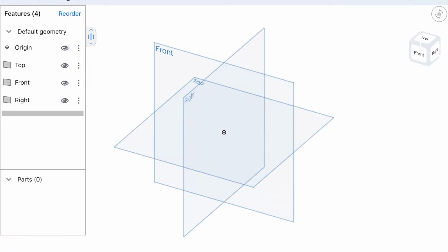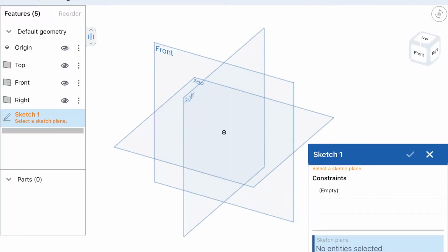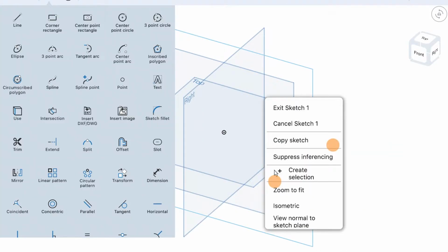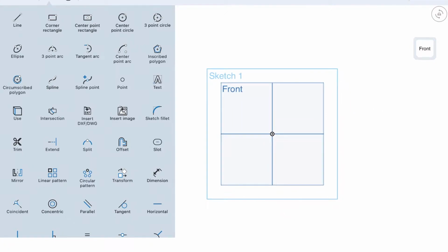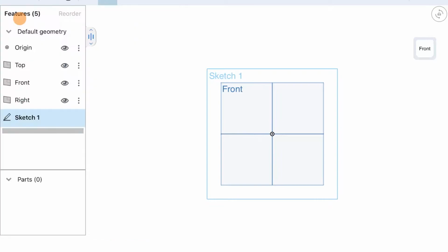Alright guys, there are lots of ways to do things, so when we do this number 3, I'm going to be showing you some new features, but I'm just going to start by making the main or the big shape. So I'm going to start from the front sketch, and I'm going to make the trapezoid. So I'm going to use the line tool to do that. I'm going to go from here to there, up, over, and then back down.